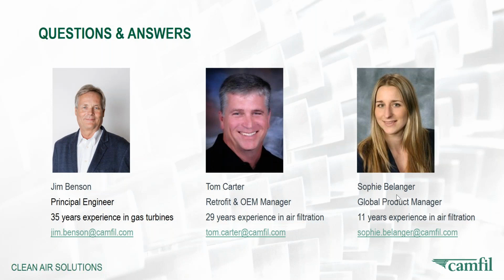Yeah, certainly the E12 recommendation has become much more common. It's been more reasonable in the past, let's say, 10 years, due to enhancements in the filtration industry. We're able to get acceptable performance. And again, we'll go back to the comments Tom made: we look at the environment. If the environment warrants E12, particularly in a coastal application, we fully agree that that's the right answer.